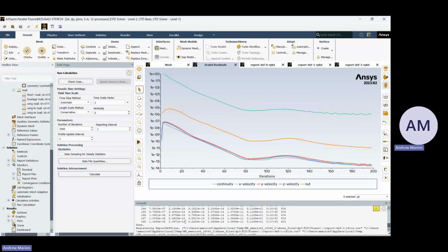If you look at your residuals, for your last value, is it the same? Once you hit -7, or if your continuity has hit -6, go ahead and hit stop at the very bottom. Does e to the -7 count? Yeah, -7 is below -6, because -7 is smaller than -6.